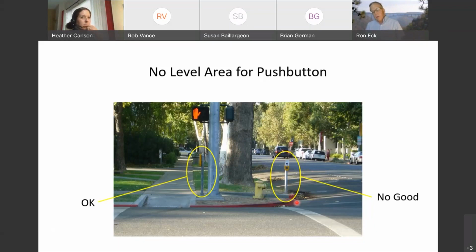But PROWAG also says where a sidewalk doesn't follow the street, the maximum gradient is 5%. And that also applies for crosswalks at street crossings. So for example, it doesn't appear to be marked as a crosswalk, but I think we'd all agree, given its location here at the corner, this crossing location is a legal crosswalk by the Motor Vehicle Code, even though it's not marked.